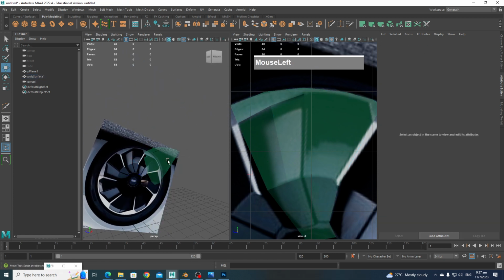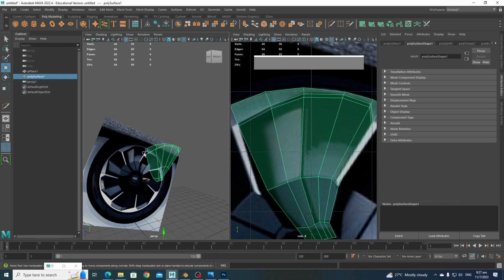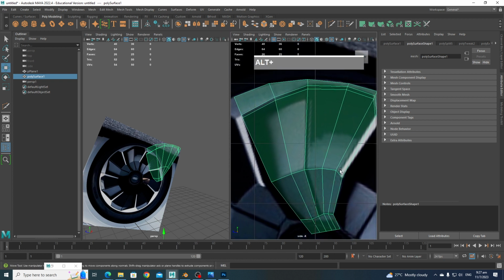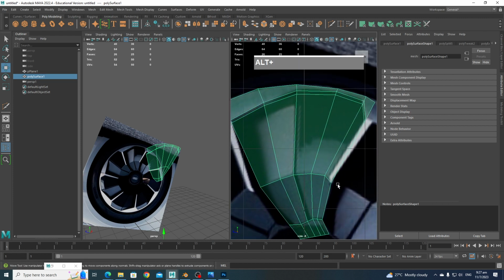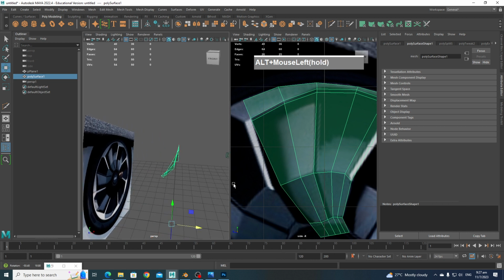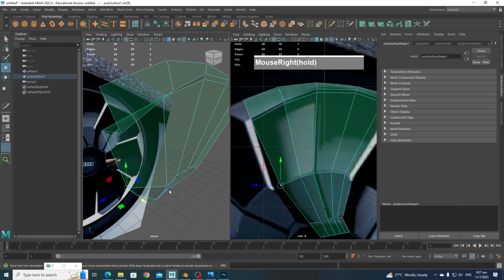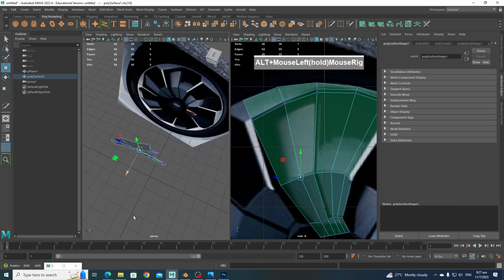Later when I finish the wheel, I'm going to create a solid version of this wheel with a solid material so that I can see where this material is going. Okay, so this is the start of the edge, and then it's so-called tapered down this way. I think this vertex needs to go down a little bit more, like that. That makes more sense.